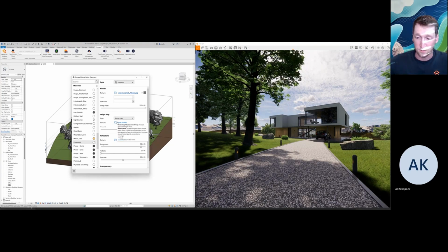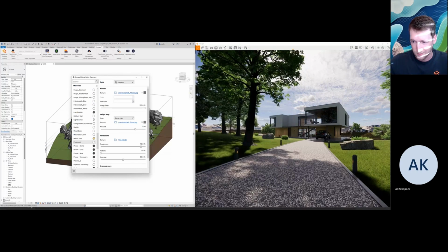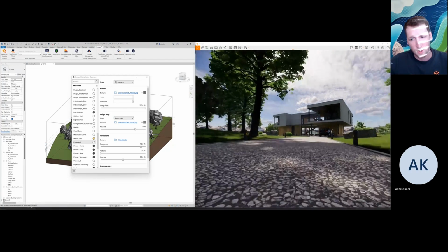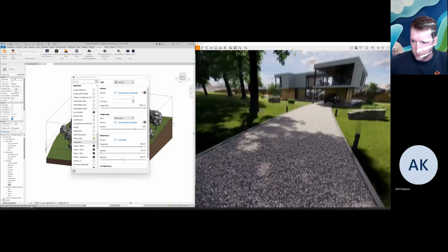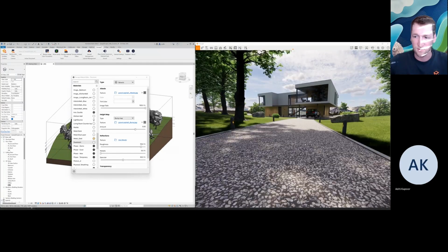And then for the height map, this is where we can show what these different material maps are. Traditionally, we'd take the bump map and the albedo map or the diffuse map, and that's pretty much where the end of those material maps would be. So for this material, this is pretty much what we would get for our final result, which doesn't look bad, but if we want to push our renderings to the next level, this is where we'll use these different material maps.